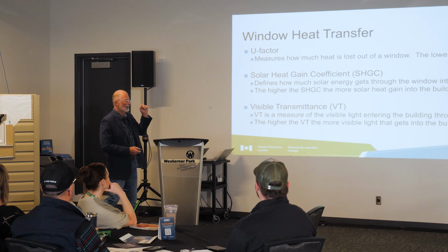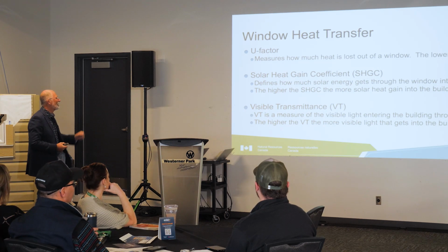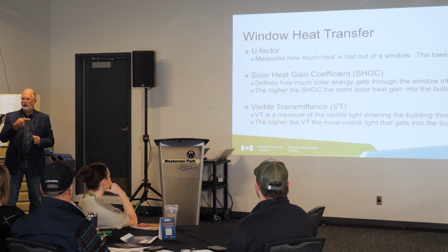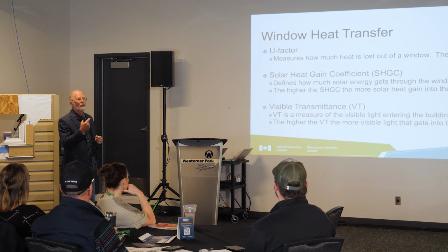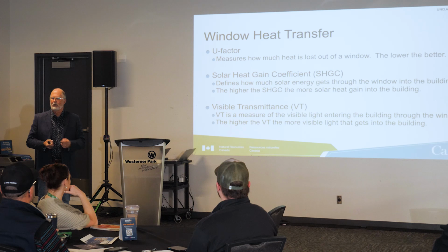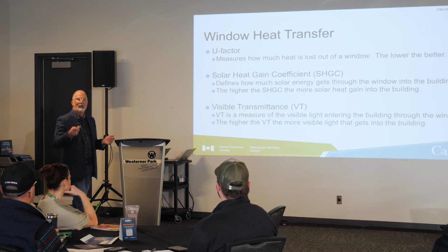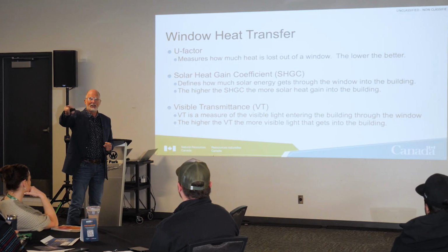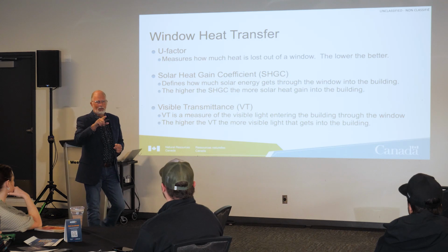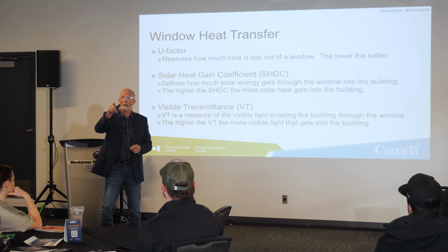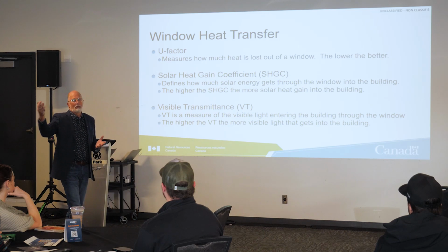So U value. What's more important, U factor or solar heat gain coefficient? Trick question. It is really a trick question. So solar heat gain coefficient, how much heat comes through the glass? Right, so if I have a solar heat gain coefficient of a 0.7, is that a good window or a bad window? Depends on where you are. If I have a 0.7 on that window and it's facing south and it's a sunny day and it's summertime, are we going to be able to stand being in this room? It's going to be pretty hot, right? But if that's a 0.2 window, then it's pretty comfortable.